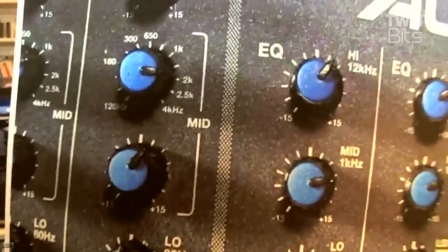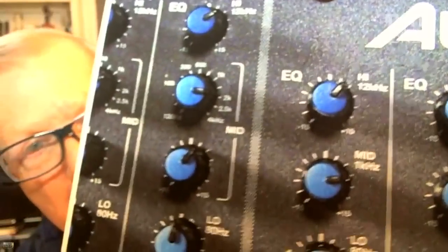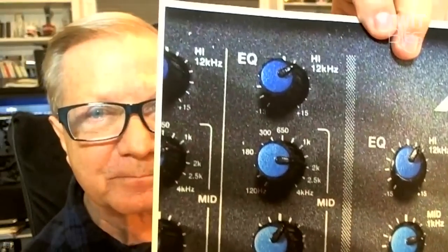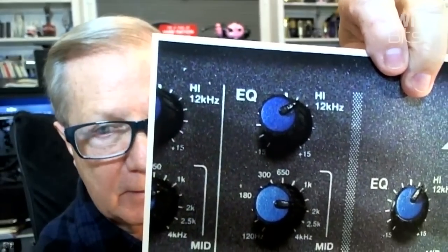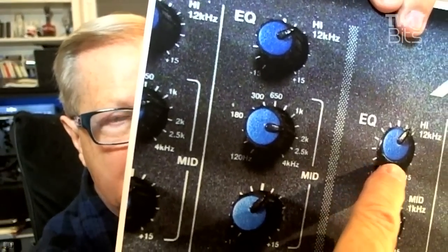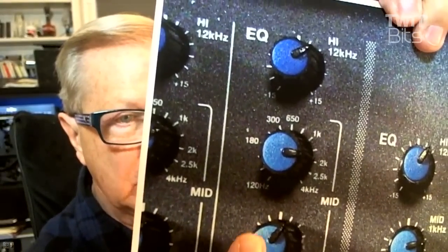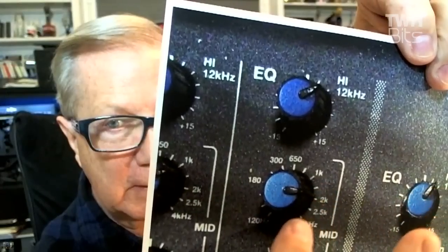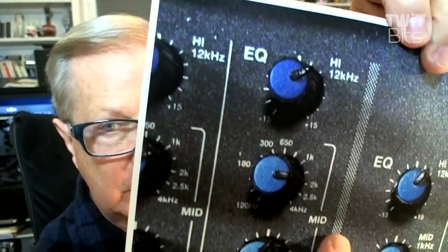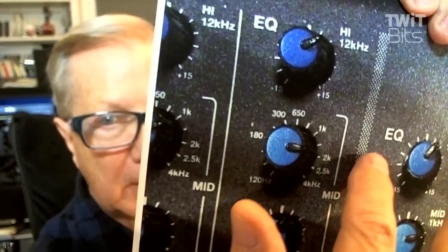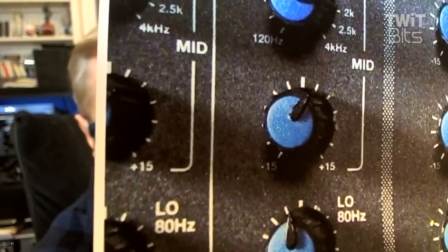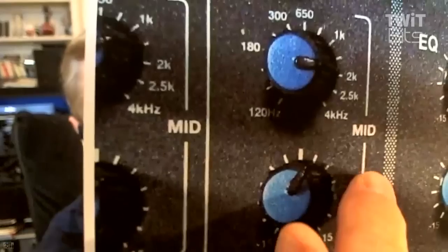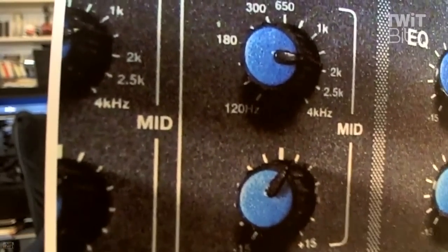So you go into using parametric EQ. It's a big word. A lot of people misunderstand it. Here you have 12K, which we're not going to use, but you have a variable mid. And what's good about the variable mids is that you can change the frequencies. You have all of these frequencies. You can change that just like you do your receiver. Most of the time, as you see here, it's going to be set on 2K. The bass is going to be set at 80 hertz, which is fine. And you can either cut plus 15 or you can notch minus 15.